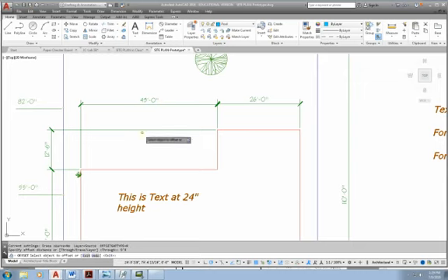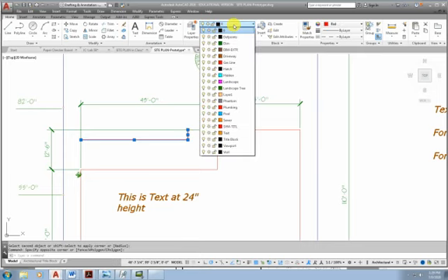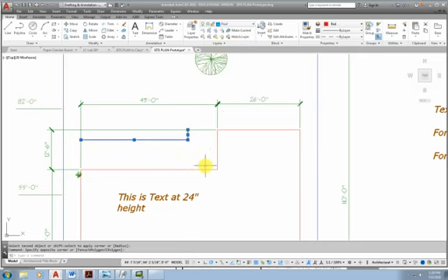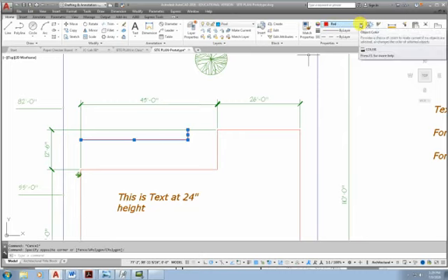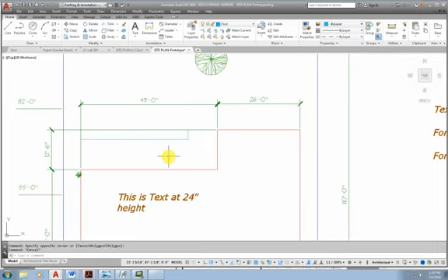You don't have to use the inch mark because it is the default. And then we'll do this one as well. And that'll give me the corner of the pool, which I will use fillet with a radius of 0 rather than trim to outline that. Now, it didn't put them on the pool layer because these are red lines. And so I'm going to highlight them and change them over to the pool layer and then hit escape. Now they're still red, so I'm going to select these lines and make sure that the properties are by layer. And now it's on the correct layer and line type.